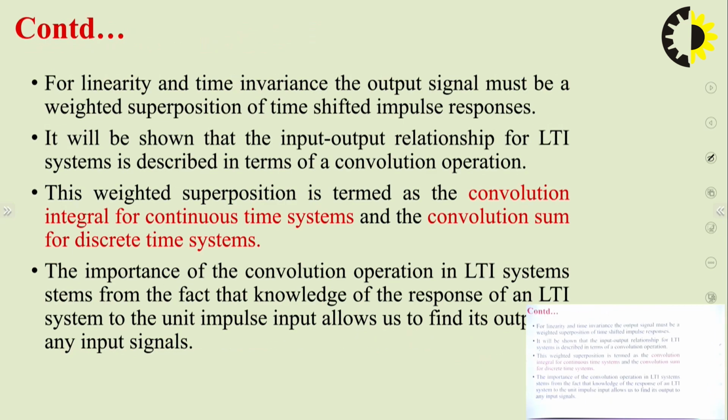Now, for linearity and time invariance, the output signal must be a weighted superposition of time shifted impulse responses. This is the condition for an LTI system. Time shifted impulse responses means impulse responses taken at various time instants. It will be shown that the input output relationship for an LTI system is described in terms of a convolution operation.